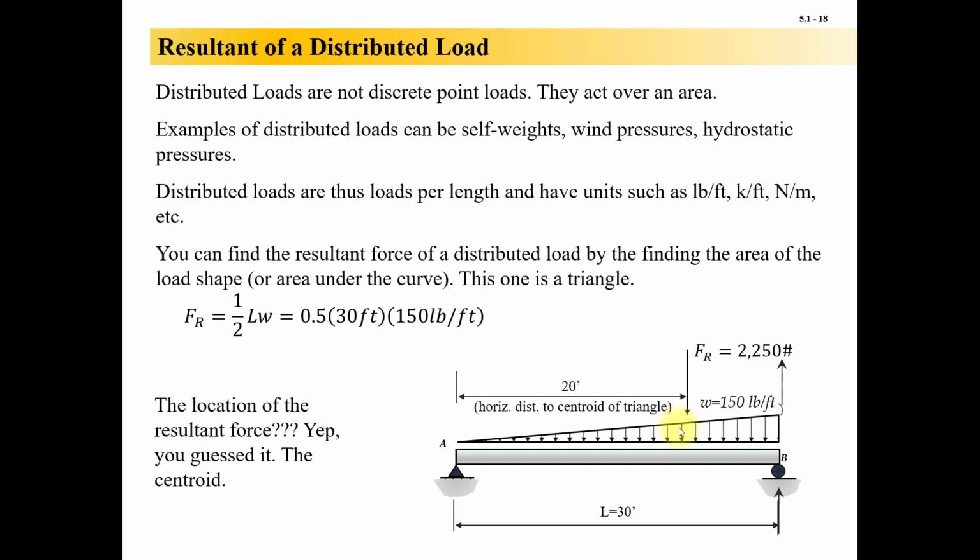If you have that uniform load, the rectangular load, like we were talking about earlier, of course it would be right in the middle. So like that self-weight of that beam, you said you knew that you could replace it with that load right in the middle. Now that makes sense. Why? Because it's actually at the centroid of the load area.